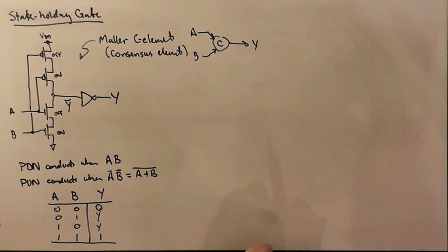You basically have to detect locally when computations are completed and data transmission is completed, and you have to communicate through what are called handshaking operations. And this type of C element is used for detecting when all of the basic operations in a given computation have finished, by waiting for all of its inputs to come to consensus.